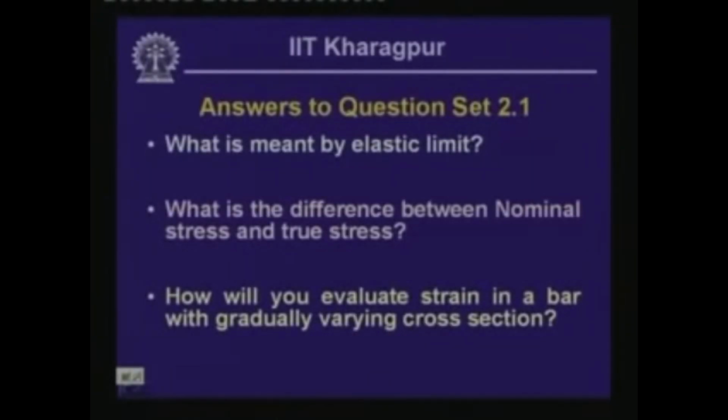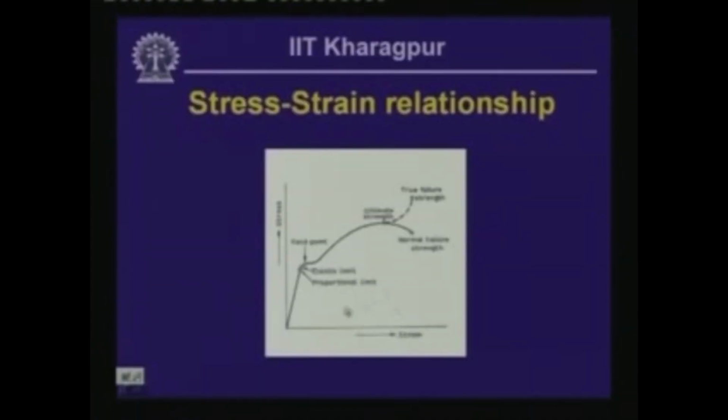Well, just now we have seen the experiment which has been performed on a bar applying a tensile pull, and then it has snapped at a point, and the type of failure you have observed we call a cup and cone failure. Now, if you remember, in the last lesson we were discussing that if we apply a tensile pull in a bar, the bar is expected to undergo deformation gradually, and at a certain point of time it undergoes failure, and that is what is represented in this stress strain curve.